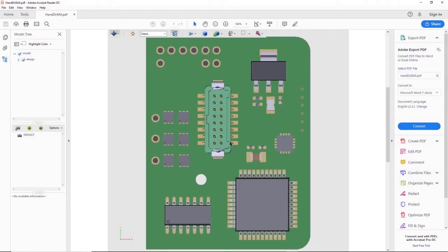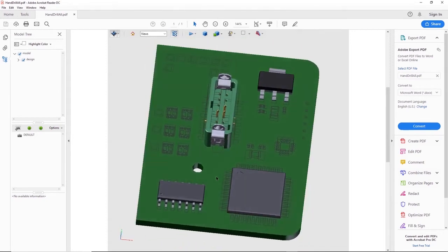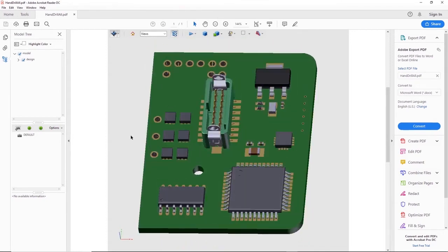When opening a PDF that was properly created with 3D content, you're given full control over viewing, similar to Expedition in mechanical tools: zooming, rotating, shading, light direction, and cross sections. Expedition creates a very detailed 3D PDF, including pre-built tree with the following objects: mechanical, assemblies, board, components, component pads, planes, traces, and vias. As you can see, by expanding the component tree, we can find and highlight parts.